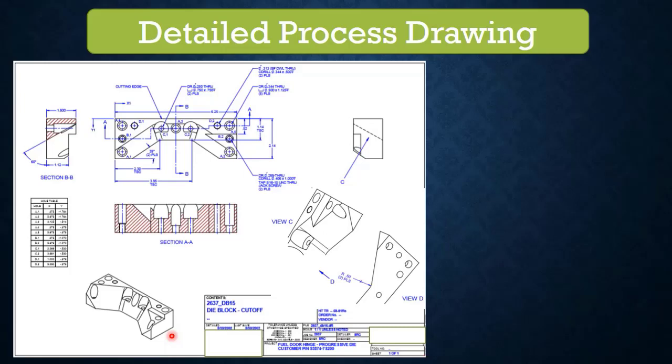During this special shape manufacturing, there are more chances to make mistakes, and those mistakes cause scrapping of the die block. So the die designer, during the design, has to make as many cut sections as possible to make it easier for the die manufacturing operator, it may be on the milling machine or CNC machine, with different angles and giving the references.